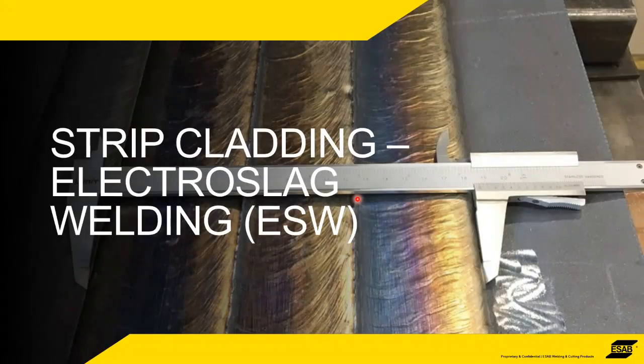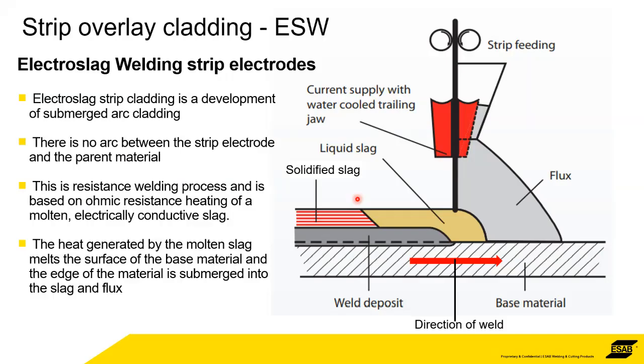The strip cladding with electroslag welding is slightly different. It's a slightly different process. Electroslag welding's been around a long time for welding things like railway lines, and it's the same process. It's the same physics that's happening, but in this case, it's a development really of the submerged arc welding process for strip. Exactly the same. You need a strip feeder machine going through some jaws. This is a much hotter process. The amount of power needed is a lot more, and I'll explain that later.